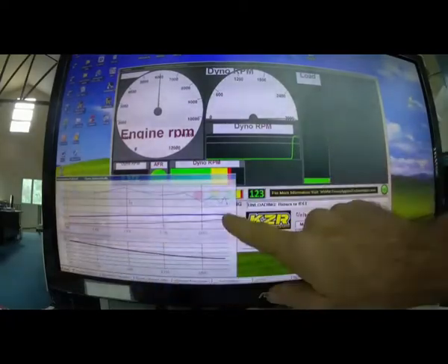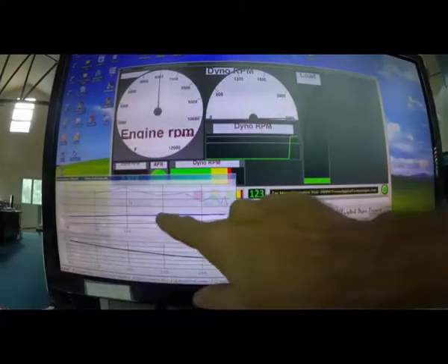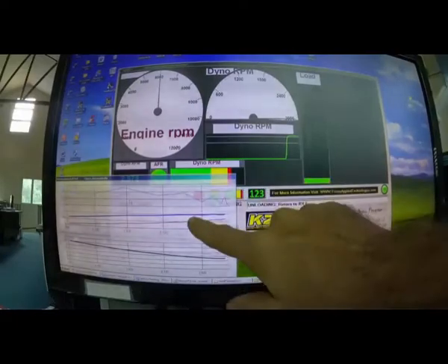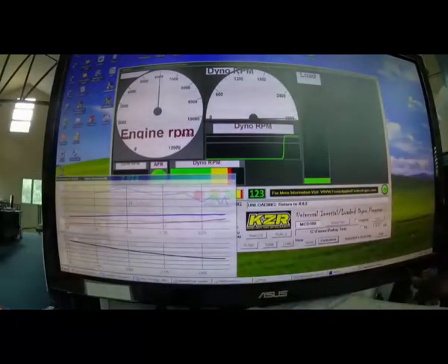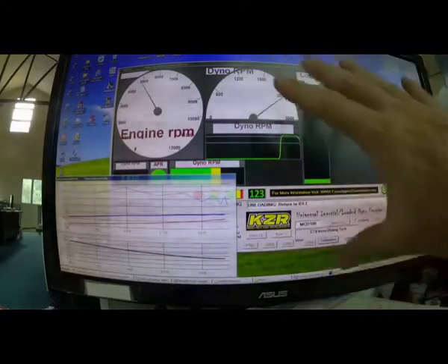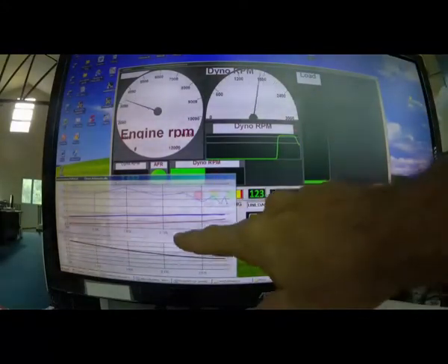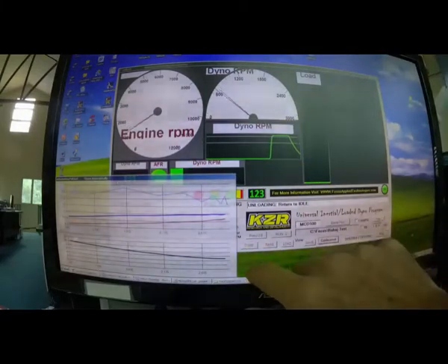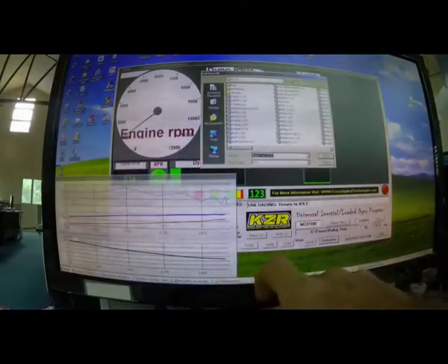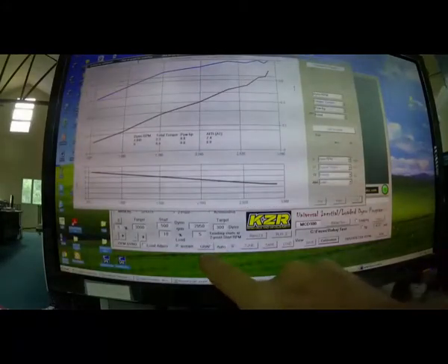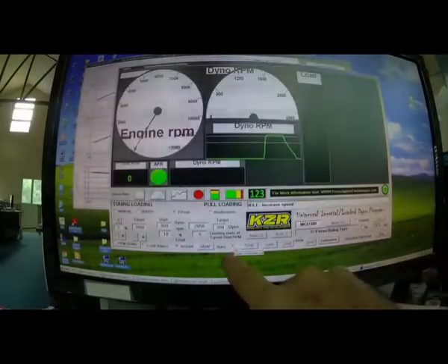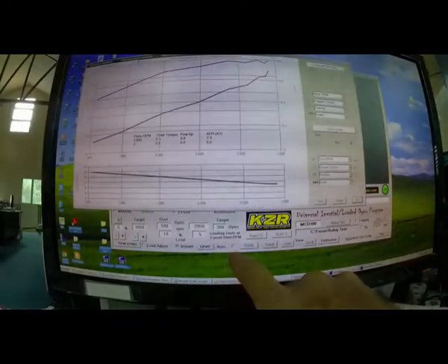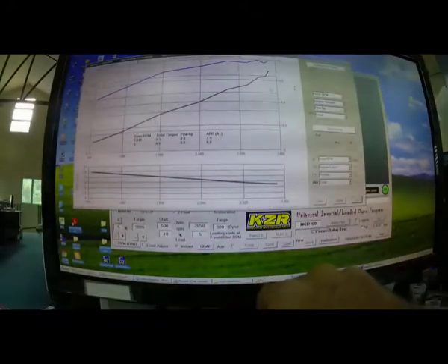We also have a different torque curve because this was the dyno torque and this is the engine torque, so it should be a factor of about a half. Okay, we're spun up. We'll spin it down. It will close this automatically, and it will open the big graph. And it opens the big graph because we've selected it to open the big graph in here. Cancel this. So there's a switch here. It says automatically graph it. If you shut this off, it will not automatically jump to this graph. If you click that on, it will automatically jump to the graph. Now you can see our power and horsepower is much smoother because we included that filtering.